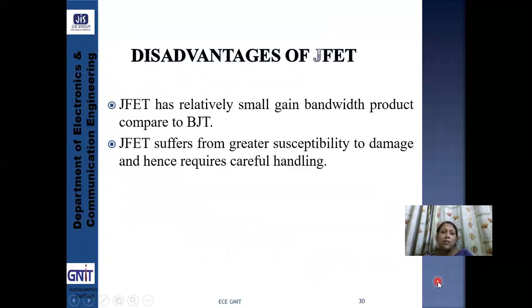Disadvantages: where there is something positive, there may be something negative. So JFET has a relatively small gain bandwidth product compared to BJT, and JFET suffers from greater susceptibility to damage and hence requires careful handling. It is costlier than BJT.